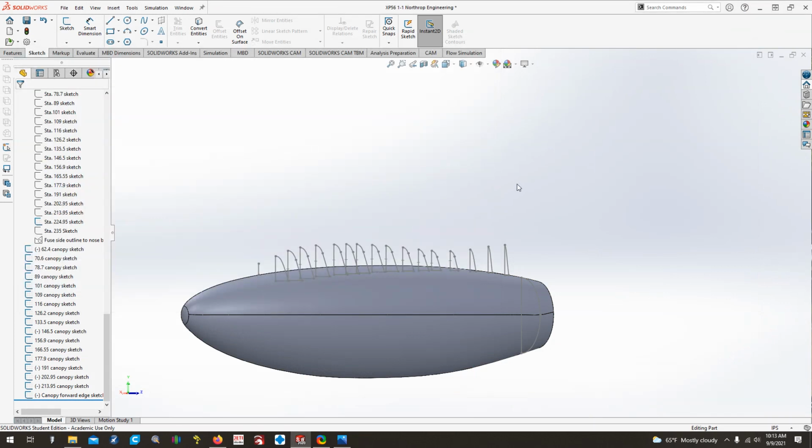I know I've got a lot of data for this that 99% of you guys will probably never be able to find for whatever airplane you're modeling. That's why in video number 1 I showed you how I typically do things, where you import a 3-view. The better the 3-views, or the more 3-views you can get, the better. You import the 3-view as a photo, adjust the transparency of it so it's more see-through, and then if you have cross sections, whether from a plastic model or from your 3-views, you can trace a sketch over them.